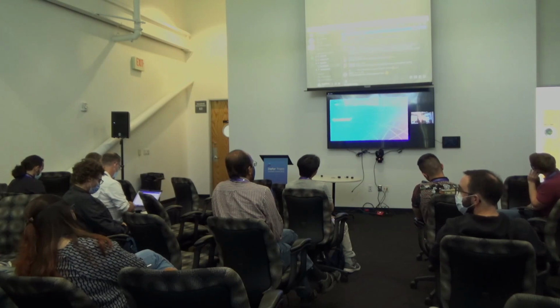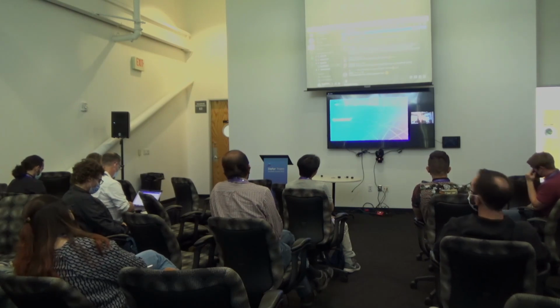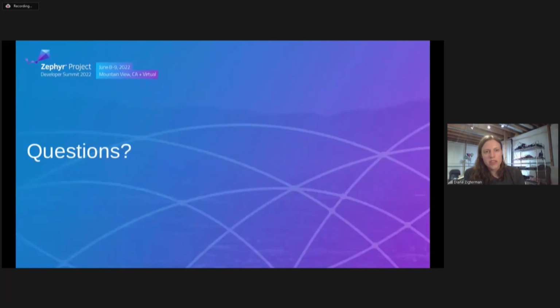So I think what we see in our Chromebooks is most of the ecosystem is generally stable at this point. A lot of the major vendors especially will go through PD compliance testing for their products. There's always going to be some random peripherals. I have a whole stack of random peripherals where they overdraw VCONN or cause VBUS voltage spikes, or one VGA dongle that won't send a good CRC if you ask it about its source capabilities. So there are random corner cases, but if you make your code robust enough, usually you can at least recover from that using the PD mechanisms available.